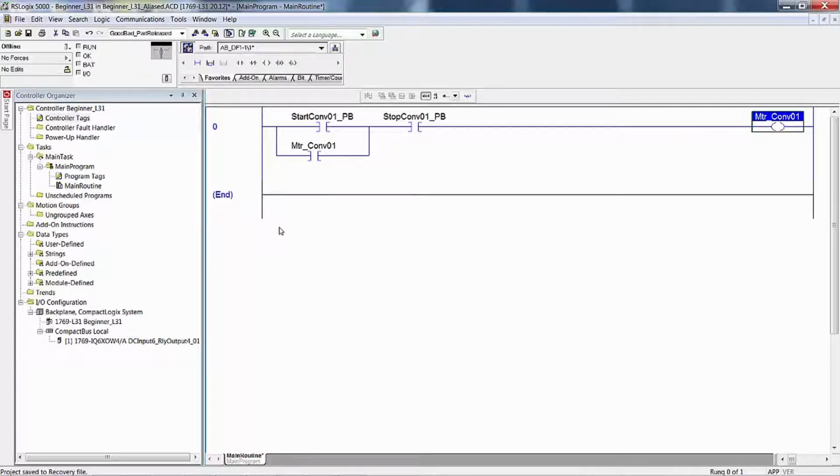These 3 tags you see in front of you, start, stop, and motor, conveyor 1, push button, and motor, can be used again in other programs. The only difference is that they're going to be aliased to different I/O, because if you have one large controller, chances are you'll have a separate controller for each distribution area. It is not hard to justify using a separate controller with distributed I/O in each of these 7 distribution areas in this big distribution center.